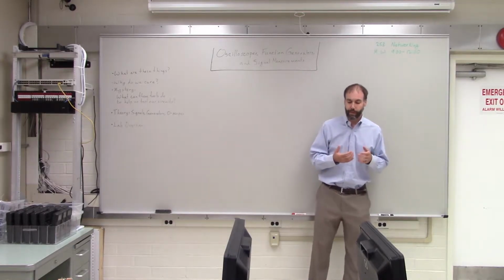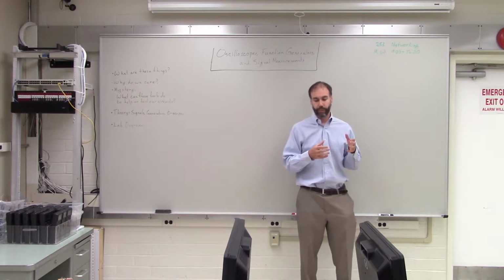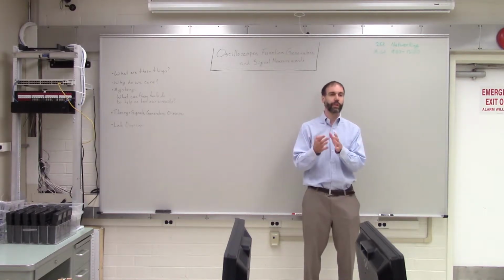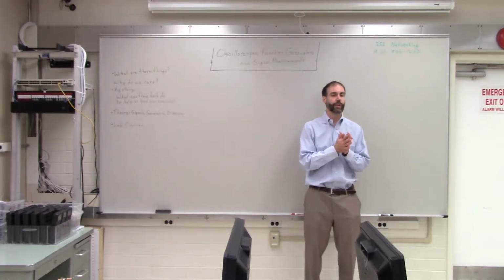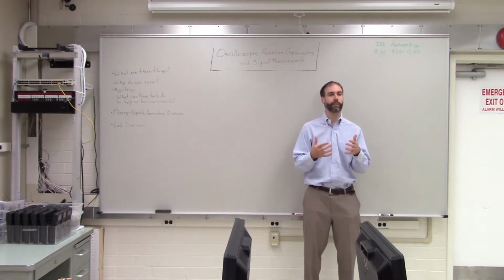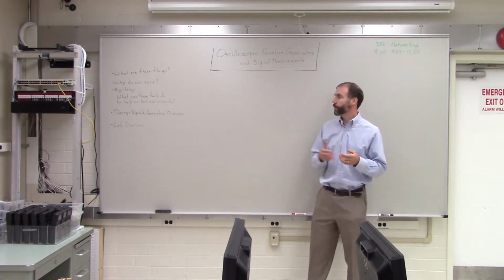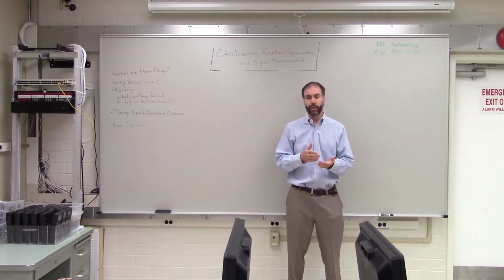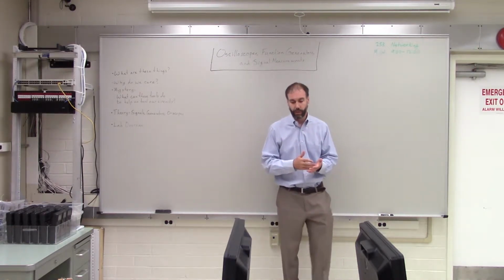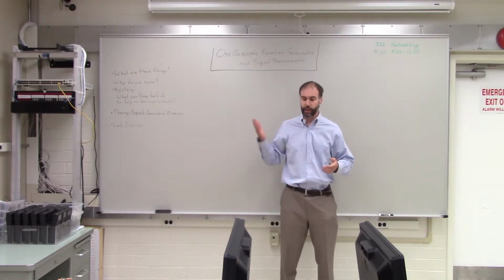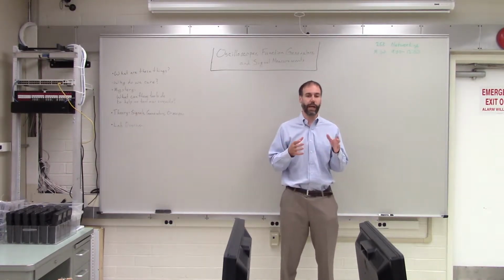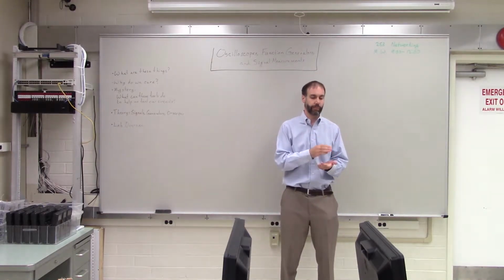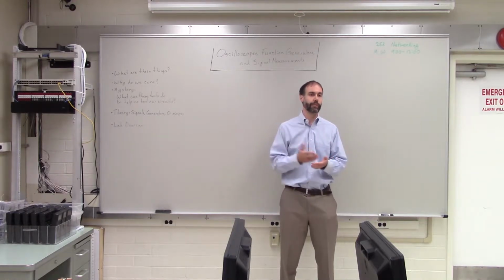So it was very inconvenient for me to actually test my software using the real device. So instead of using the real device, I needed something that could stand in for that. And a function generator did that nicely. It turns out that the way that the laser pulses were displayed from the actual laser was with voltage pulses. So every time the laser fired, a little voltage pulse was created.